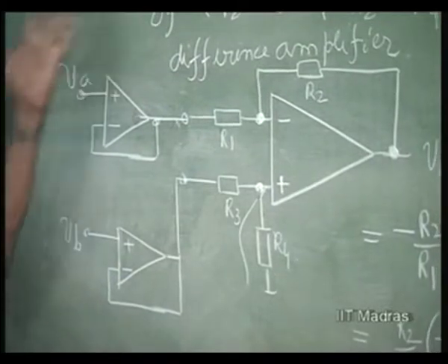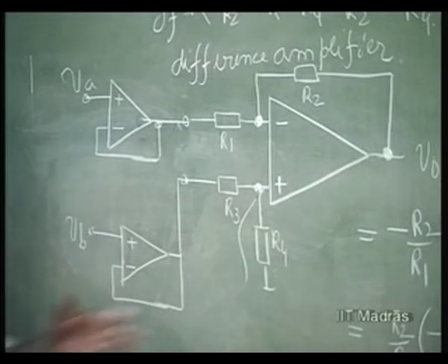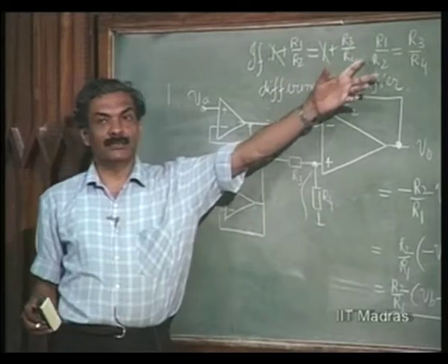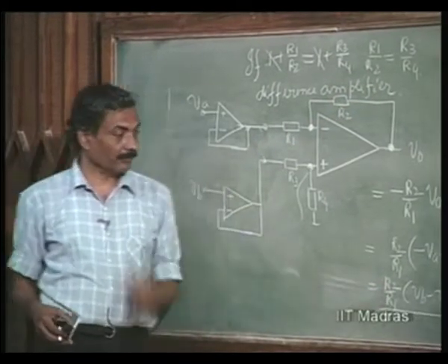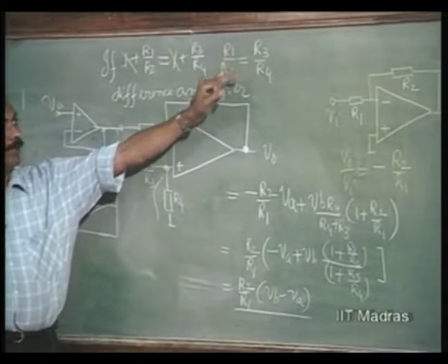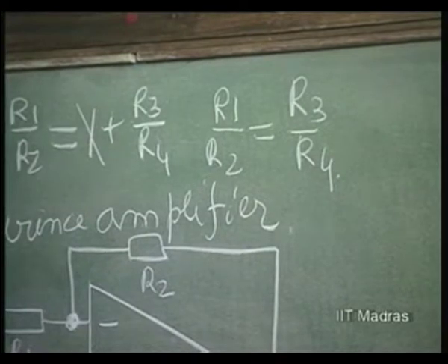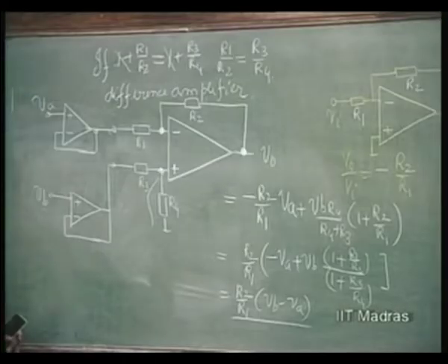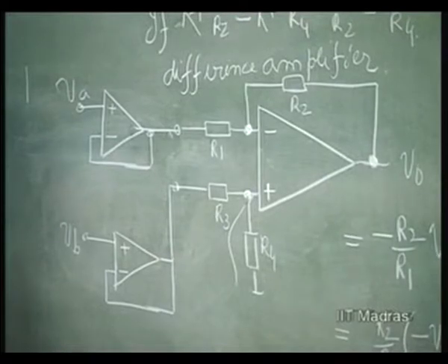So, now these three op amp configurations can act as a fairly good instrumentation amplifier with a gain of R2 over R1. But you know, this condition has to be satisfied: R1 by R2 should be equal to R3 by R4. Now, say I have a near-ideal op amp, but the resistors I have chosen are just nominal resistances with some amount of tolerance.